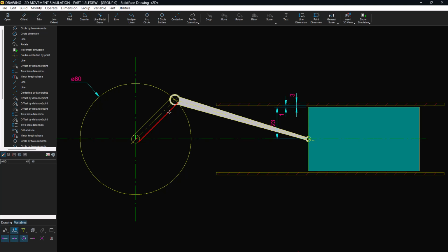Both actions will be stored in the command list and cause an overhead during each reprocessing cycle. In other words, for each processing of the list, the geometry will be deleted and then a new one built. Instead, when possible, choose to delete the commands directly in the list of commands. This action will also force you to delete all subsequent commands and return to the original stage at that point. The inconvenience is that we can only delete the commands with errors and the following ones. That's why it's important to test each stage of construction. Therefore, if errors occur, a minimum of commands will be deleted to return the geometry to the desired intent. In Part 2, we will show how to retrieve geometric information from geometry and use logical conditions to create test messages.